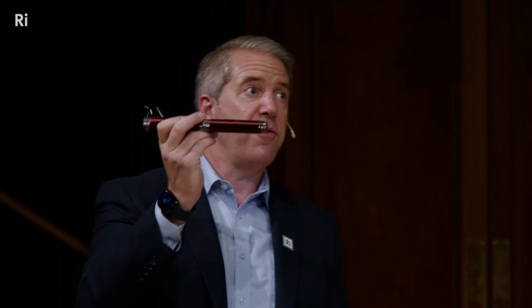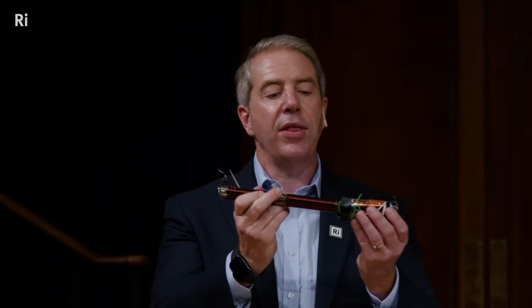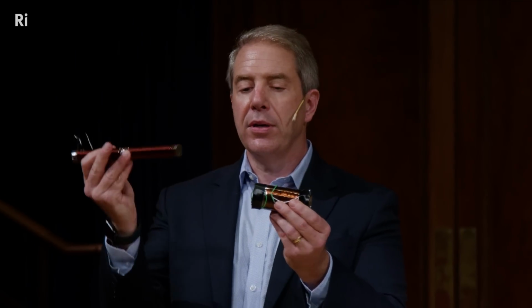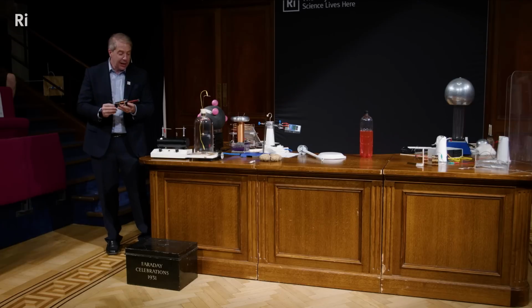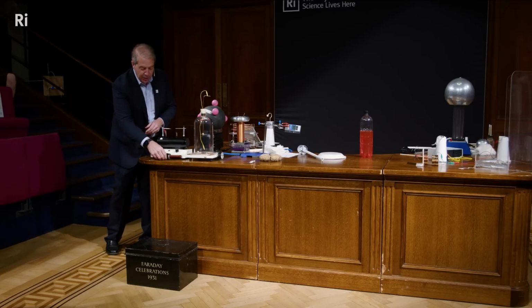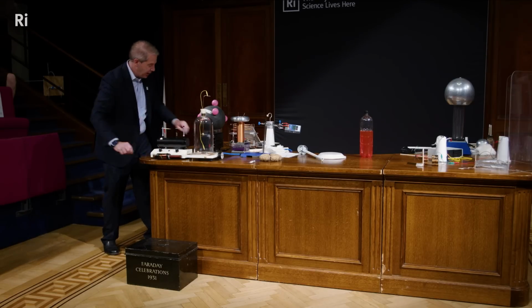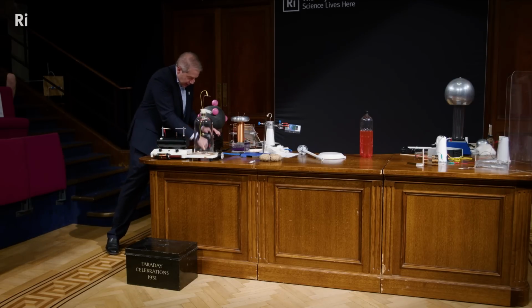That's the first thing that this does. The second thing is the voltage this produces is related to how fast we change the current. So the faster we can change the current in this, the higher voltage we will get on that. And so our core is to do lots of currents, high turns, switch it fast, and that is exactly what is inside of this machine. And I'm just going to turn it on so that you can see.